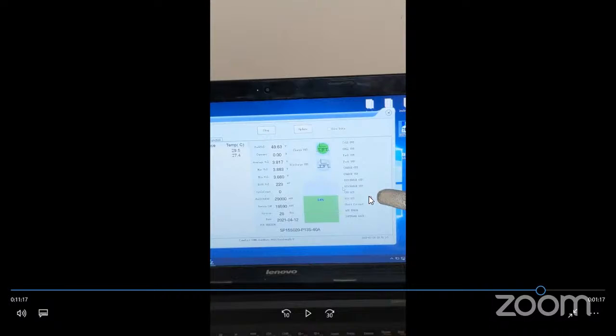It will not allow the battery pack, the motor, to draw more current from the battery pack. Or if you're going on a hilly climb and there's a lot of load on the vehicle which the motor is not able to take, that's where this functionality plays a role.